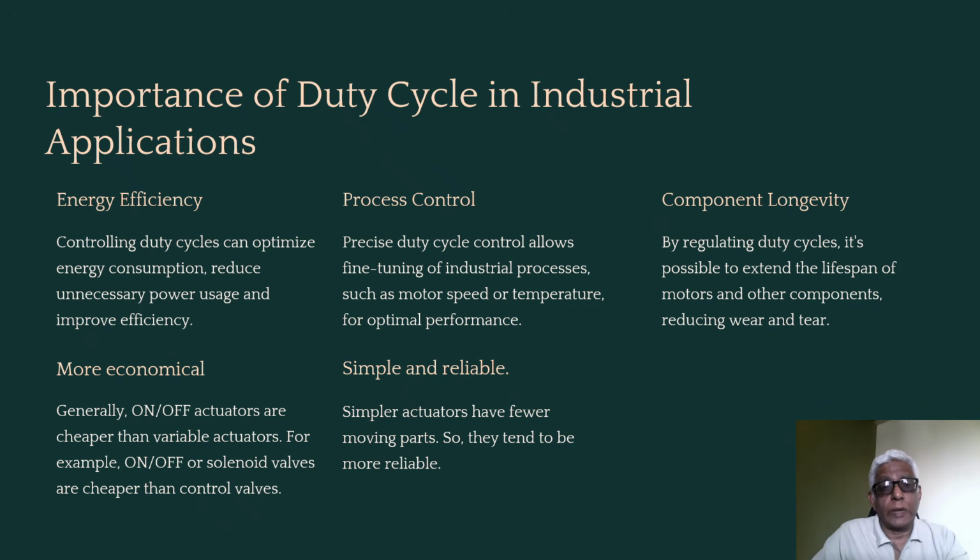But please bear in mind that certain things duty cycle control cannot achieve, such as flow control. If you try flow control with a duty cycle controller, you will have pulsating or interrupted flow, which is not a good thing. So just keep in mind, it has its uses. It's very useful and very economical, but there are certain things like flow control it cannot do. Okay.